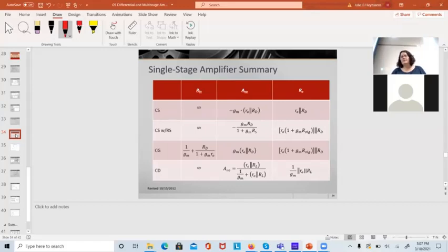This chart will help you out if there's a common source, source resistance, common gate, common drain. I tend to put more of these in there and less of those, because these are easier to figure out. Diff amps and cascodes. You're more likely to see more of the red stuff than the common gate and the common drain, maybe as an output stage or something like that.